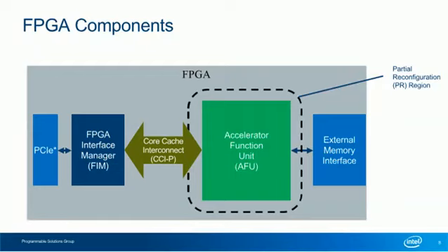If you're designing the AFU using OpenCL, then you don't need to know the details of how the CCIP interface works, as that is abstracted away in the OpenCL flow. However, if you're designing your AFU using the RTL flow, then you will need to ensure your AFU conforms to the CCIP standards. The entire AFU is located on the FPGA in the partial reconfiguration region. This allows the FPGA hardware to reconfigure the AFU bitstream accelerator functionality. When using a discrete FPGA on a PCIe board, the AFU will also have access to external memory controllers, which are connected to off-chip memory, such as DDR4 memory.